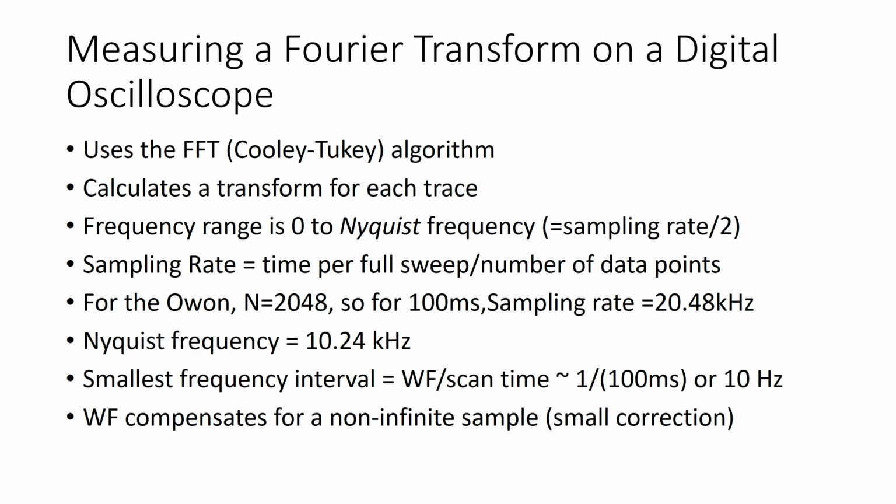What about the smallest frequency interval you can measure? Well, this is just related to the longest time that you sample. It can't be any faster than 1 over the longest time. So in the case of having a 100 millisecond scan, it would be about 10 Hertz.